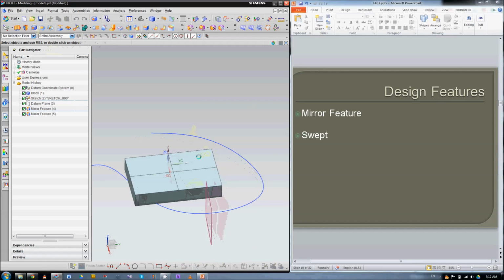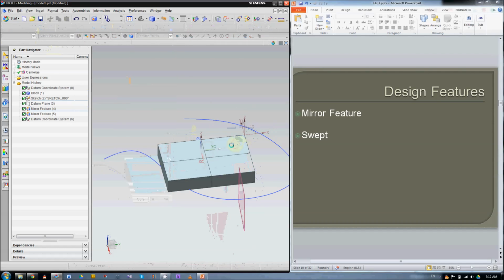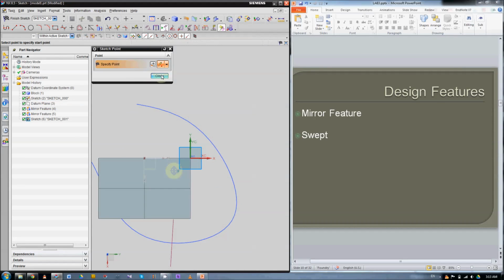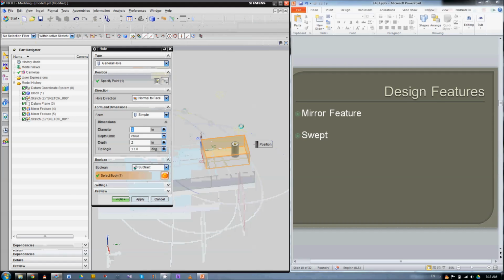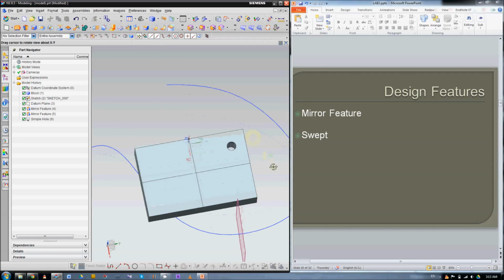okay, let's first maybe make a hole here. You can first make a hole. I think there's a point. Finish sketch. Then we can define the parameters, diameter. I'll just leave this for 1 inch, so you can see a hole there.